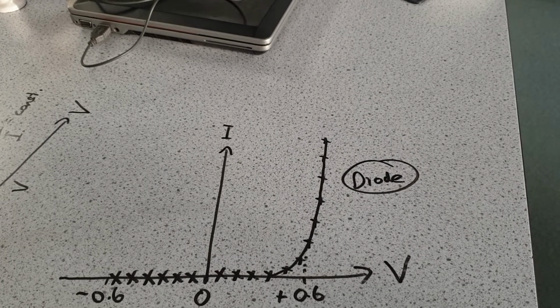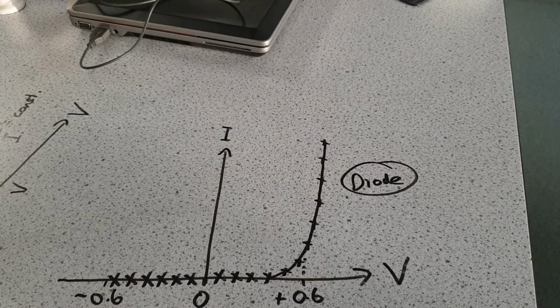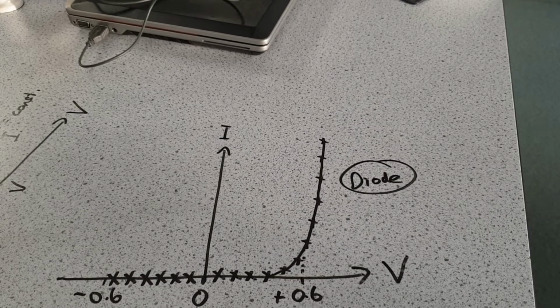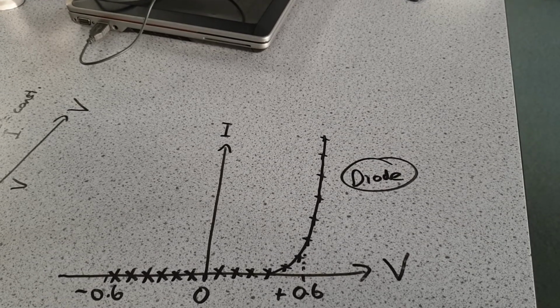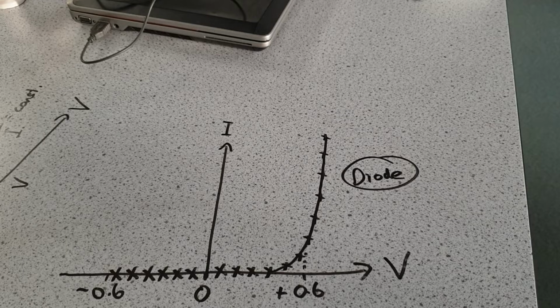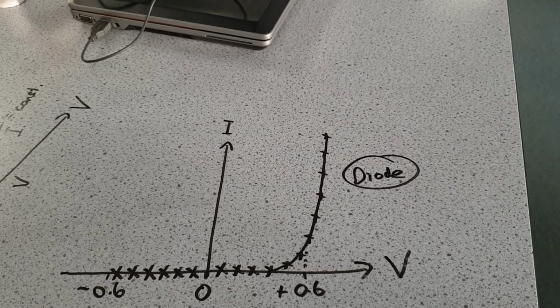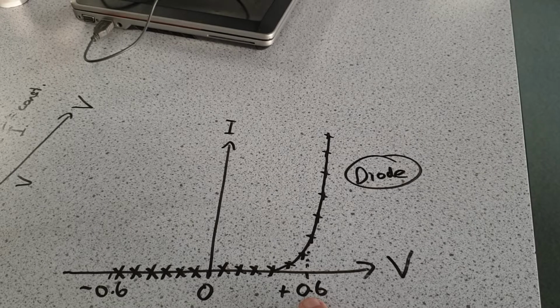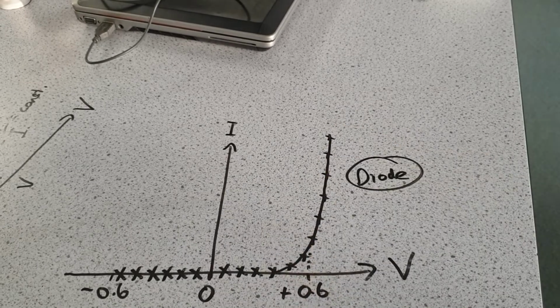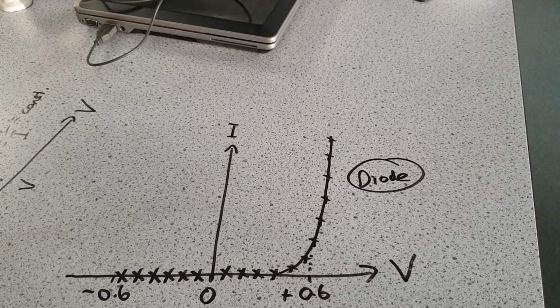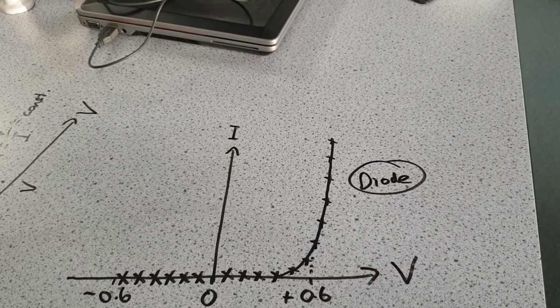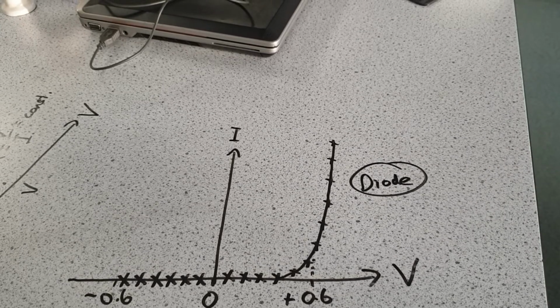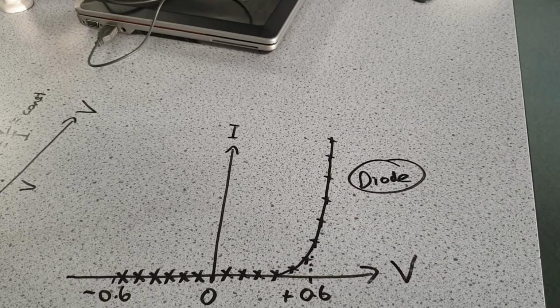So, for instance, you might want a warning light to come on very suddenly, depending on temperature or whatever it is that's setting the warning light off. If a diode is part of that circuit, it can produce a very sharp switch. So this switching characteristic of a diode is sometimes used in a circuit as well. There are other uses of diodes, but they're the main uses.